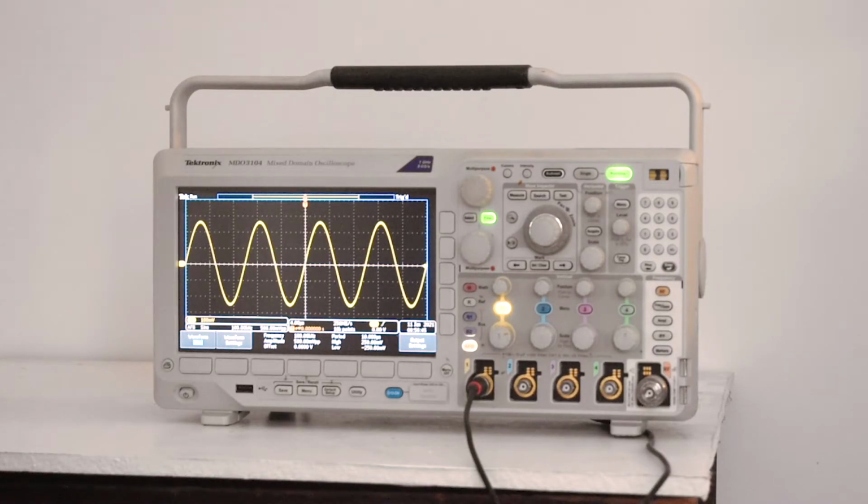The solution is to press a channel button, then the soft key associated with bandwidth, and restore full bandwidth. Either that, or, if appropriate, press default setup and start over. Depending on what you are doing, you may want to press default setup before starting or during a project, especially if nothing is working as expected.